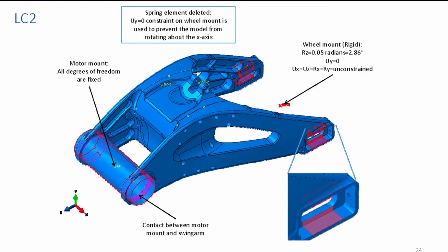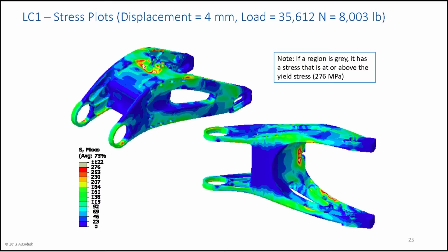We can do better. So for the first iteration we said, okay, what are the constraints that we can't change, right? And those are things like where it attaches to the structure, where the rear wheel is attached to the axle, where the suspension attaches. These are fixed things, we can't change that. So let's lock those down. Those are constraints. And then we do an analysis to figure out what the loading conditions are. If you guys aren't familiar with finite element analysis, this is basically a heat map of the stress. So red areas have a lot of stress, blue areas have very little stress, and green is somewhere in between. So you can see here there's a high area of stress concentration. Over here in this blue area, there's not much going on.